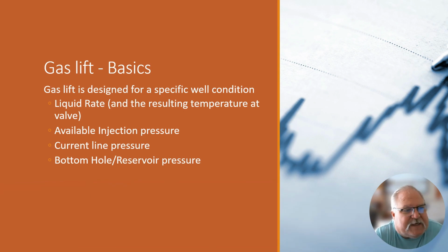So let's first of all talk about some gas lift basics. Gas lift is really designed for a specific well condition, liquid rates, and the resulting temperature of those liquid rates, because that liquid pulls the temperature up to the valves. Available injection pressure, current line pressure, bottom hole reservoir pressure. So you design it for a point in the well's history, and then you try to expand or add valves, do all sorts of different things to encompass that well as it changes, as it goes through these changes. But you can only do so much of that.